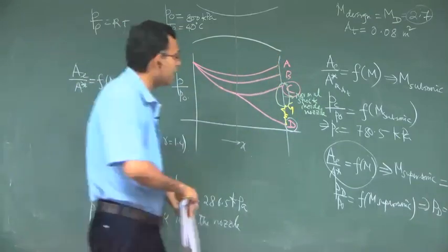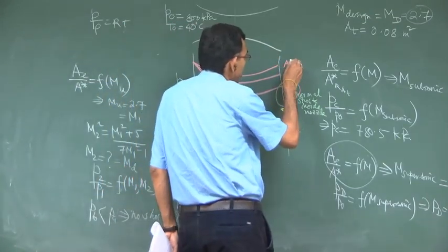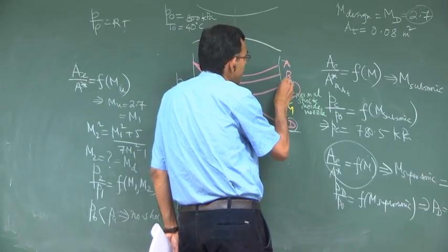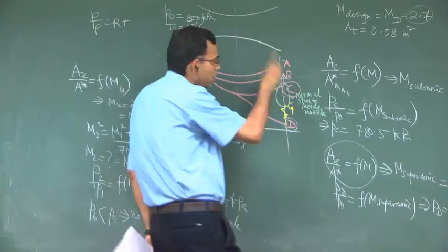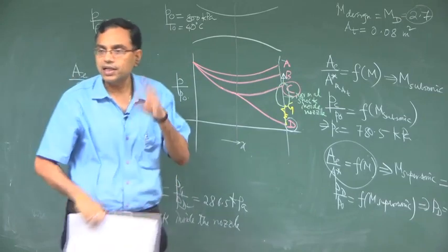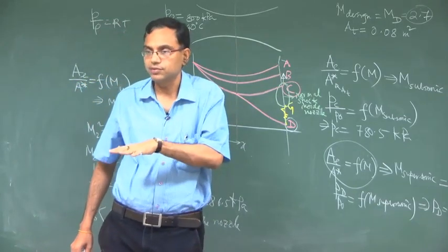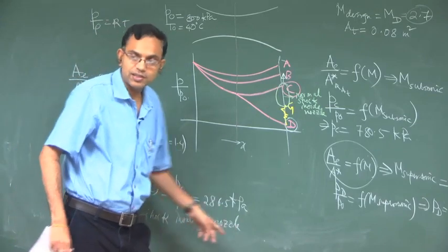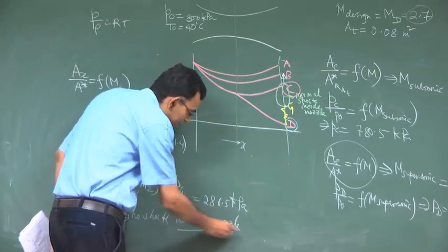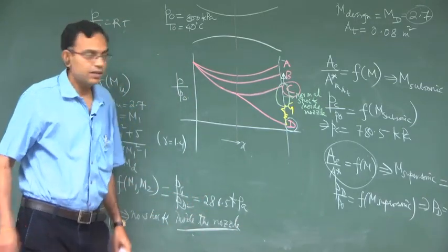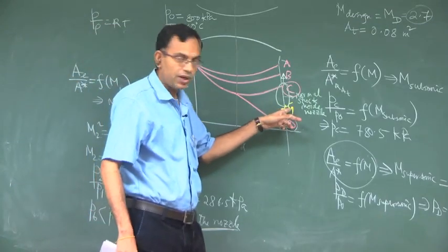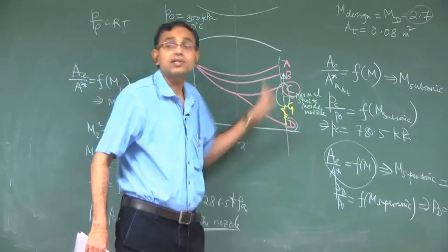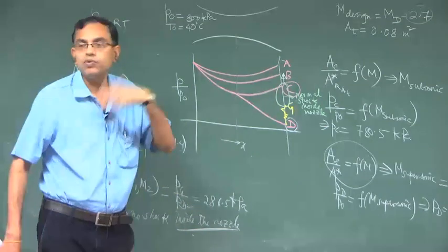So, you are very correct that for P greater than Pc, there is also no shock inside the nozzle, but in that case there is no shock outside the nozzle also, there is absolutely no shock. So, that extra qualifier inside the nozzle tempts us to pinpoint this region where there is shock outside the nozzle or expansion wave outside the nozzle.